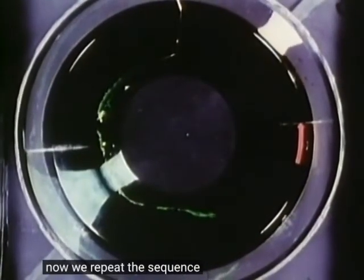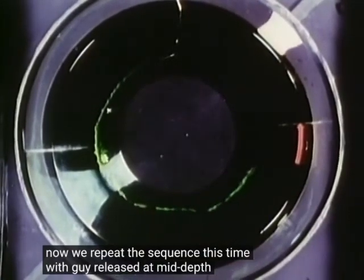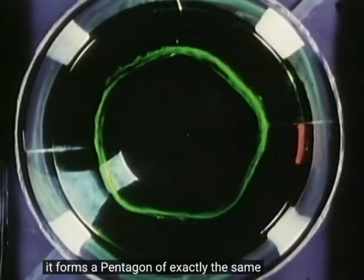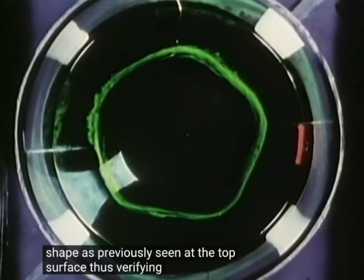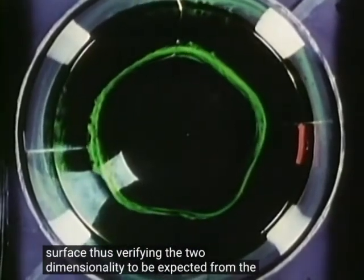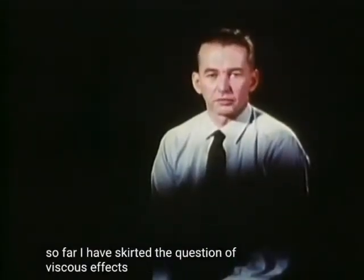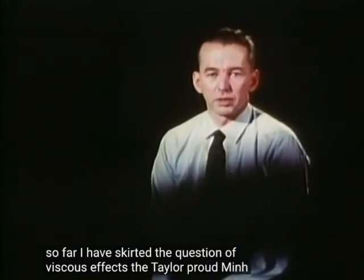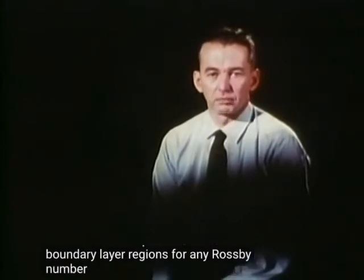Now we repeat the sequence, this time with dye released at mid-depth. It forms a pentagon of exactly the same shape as previously seen at the top surface, thus verifying the two-dimensionality to be expected from the Taylor-Proudman theorem. So far, I have skirted the question of viscous effects. The Taylor-Proudman theorem, for example, does not hold in boundary layer regions for any Rossby number.